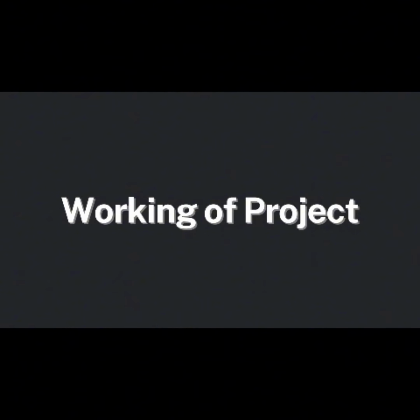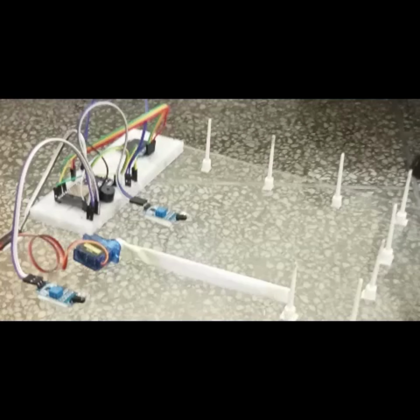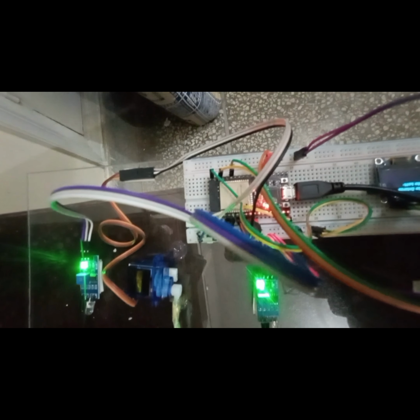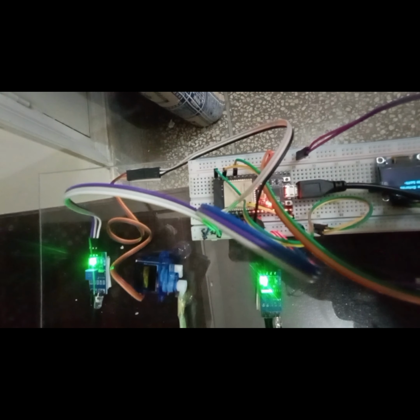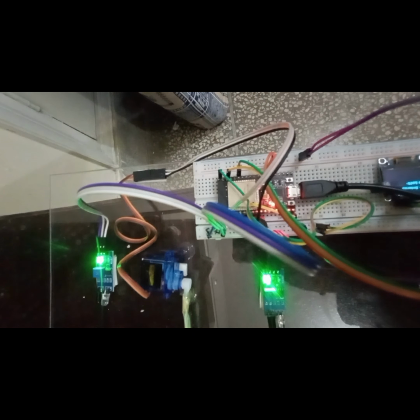And the final conclusion about this project: the project works by utilizing three IR sensors to detect and count objects passing through a door. When an object approaches the door, the entry sensors trigger the opening of the door via the servo motor. The exit sensor counts the object as it passes through, which acts as the brain of the system, handling the logic for sensors, the servo motor, and communication with the display. It has flexibility, allowing us to easily manage multiple components efficiently.